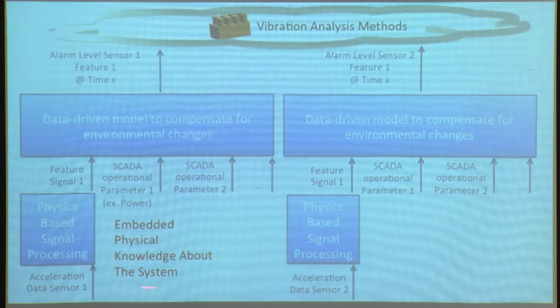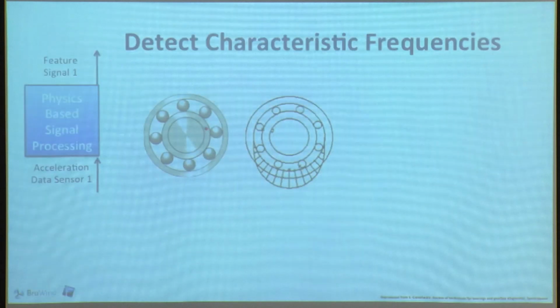On top of this, I will go into detail about how this works in the next slide. I do a kind of classification where I take the operating conditions and filter them out, such that I can make different periods in time comparable to each other, and I can track what the asset is doing. From this, I extract a feature about the health linked to the gearbox, for example the first planetary stage measured on this sensor. I will do this for all sensors, which will give me different features. So I will get insights into system condition.